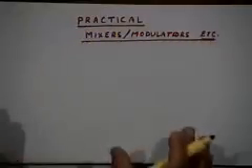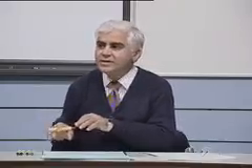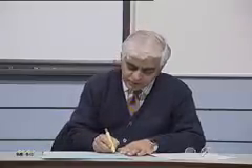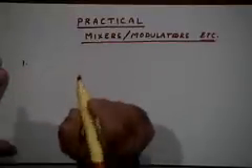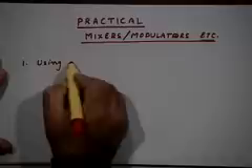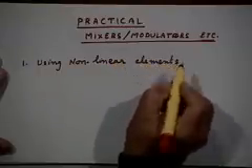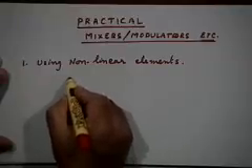Why? Because I wanted to give a brief idea about these things in this class, which is the reason why I put "etc." in the title of my lecture today. That is, superheterodyne receiver, etc. Now I'll just have a very brief discussion here. One is we can realize these kinds of devices using nonlinear elements. What do we want to do? We want to multiply two signals. It could be the message with the carrier, it could be the incoming carrier frequency signal with the local oscillator signal. These are the kind of things we want to do.